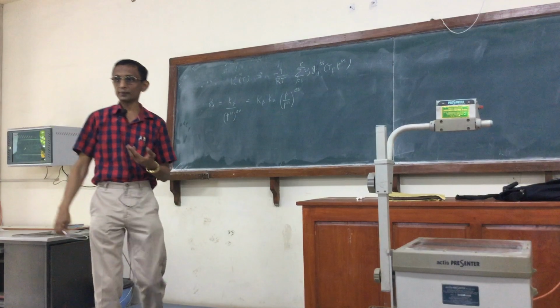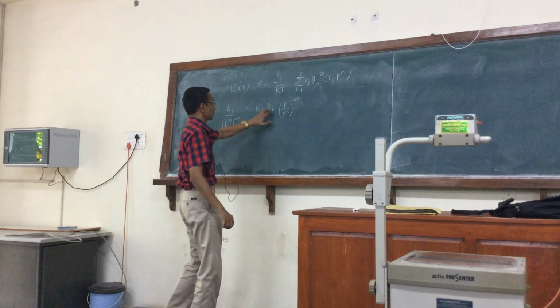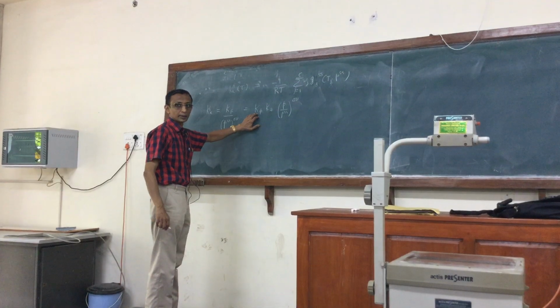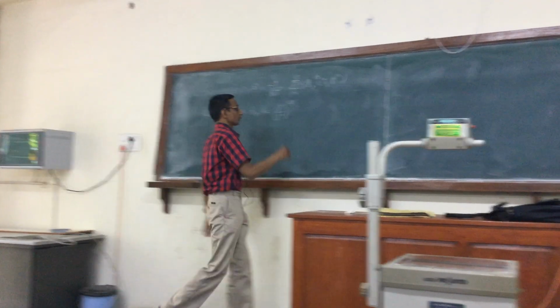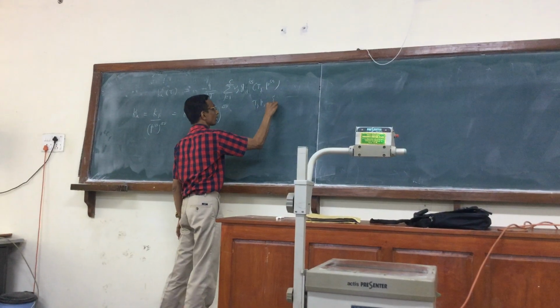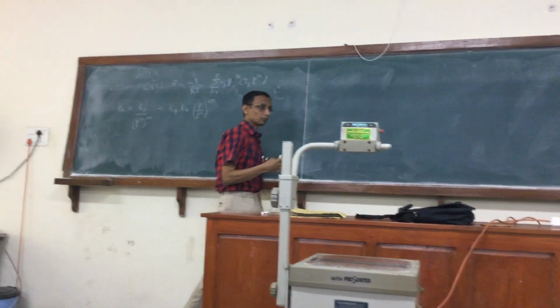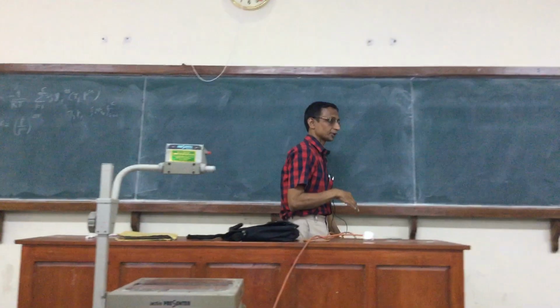So what I was pointing out was, this is the mole fraction equilibrium constant, the composition based equilibrium constant. Now what we assume is that apart from the temperature and pressure, the initial number of moles of all the components in the reaction is given.